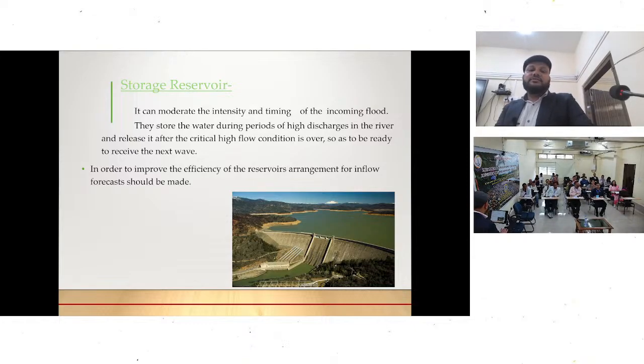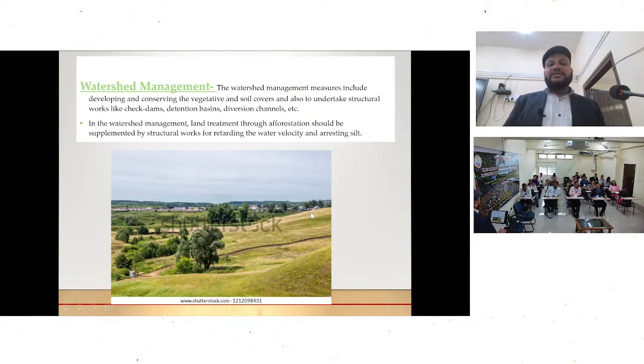Then storage reservoir, meaning dam. It moderates the intensity and timing of incoming floods. They store water during periods of high discharge in the river and release it after the high flood is past. It stores water in the high flood season and mitigates the flood, and during the lean season it releases the water for irrigation, agriculture and other things. And watershed management is also there. Watershed management includes developing and conserving vegetative and soil cover, and also undertaking structural works like small check dams.